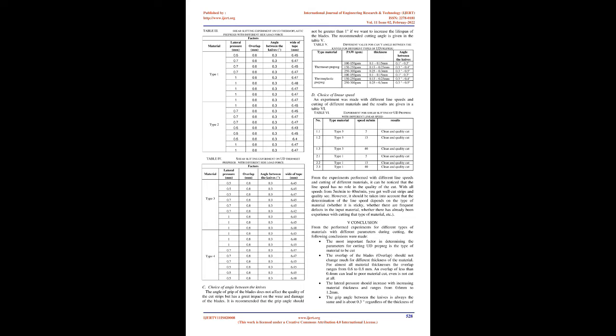From the picture it can be noticed that in this case the UD preform is cut but the foil remains uncut, which leads to a halt in production. To solve this problem, the lateral side pressure was increased from 0.7 mm to 0.9 mm, after which the problem was completely solved. Fig. 5: different types of defects with shear cutting.